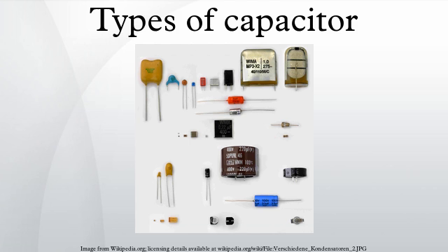Bipolar aluminum electrolytic capacitors contain 2 anodized aluminium foils, behaving like 2 capacitors connected in series opposition. Electrolytic capacitors for special applications include motor start capacitors, flashlight capacitors and audio frequency capacitors.